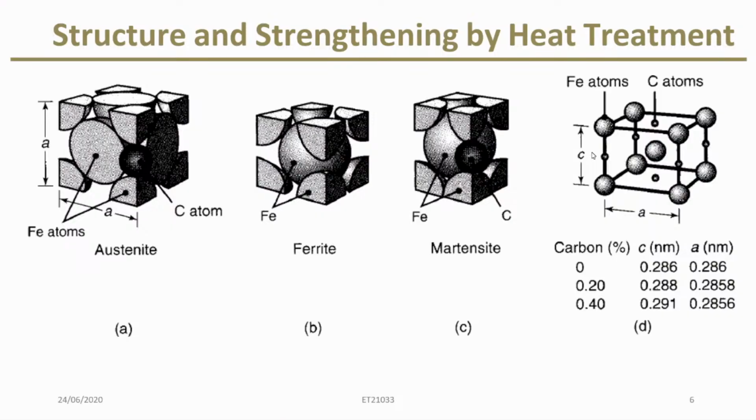But raw martensite is also brittle and stressed. So we temper: reheat below the critical temperature to let carbon redistribute, relax stresses, and trade a little hardness for a lot of toughness.